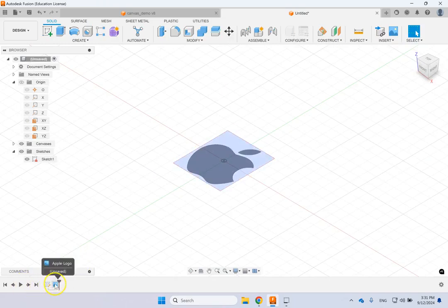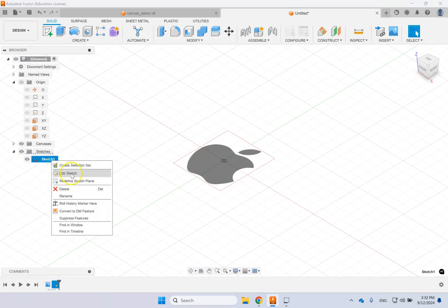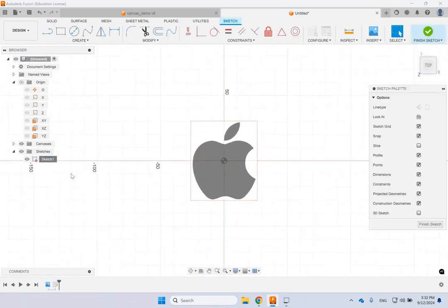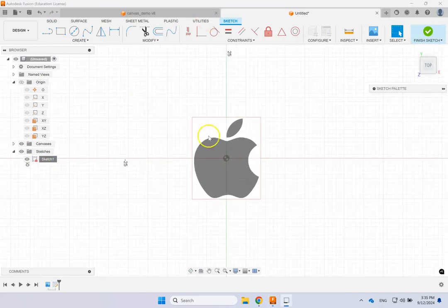So if I want to use that picture, I have to bring it first, then create the sketch, or I have to move this sketch here to the left of the canvas. Can I reorder this order of operation? Yes. So here I grab this picture and move it to the left, and there we go. So this is now like you first brought the picture, the canvas, and then started the sketch. Now if I go to the sketch, I should be able to see the picture. There we go. And I should be able to recreate the profile using the sketch tool.